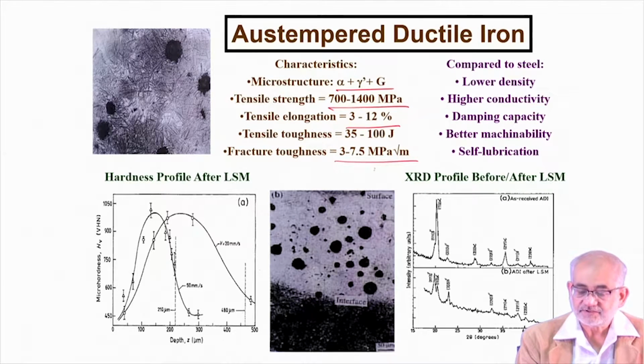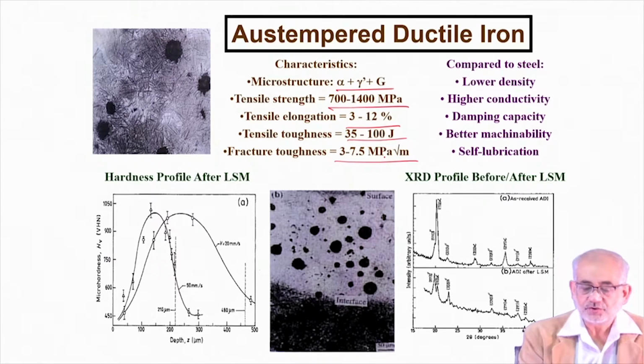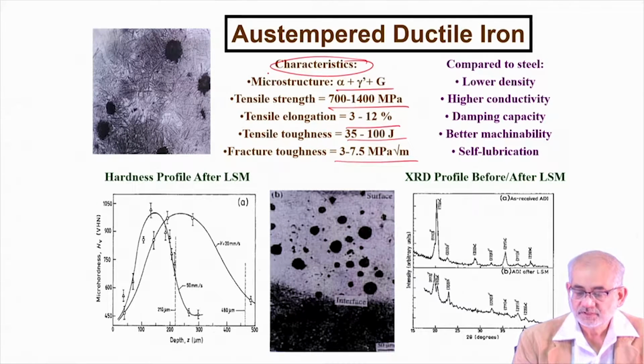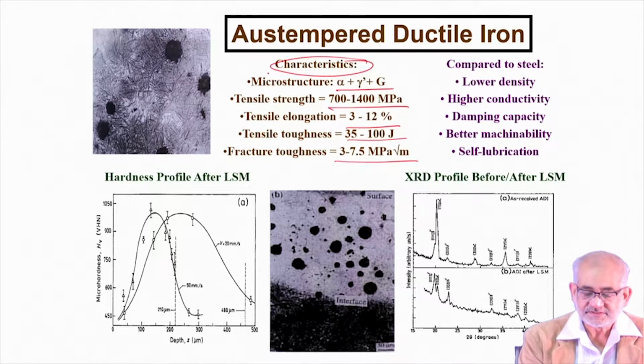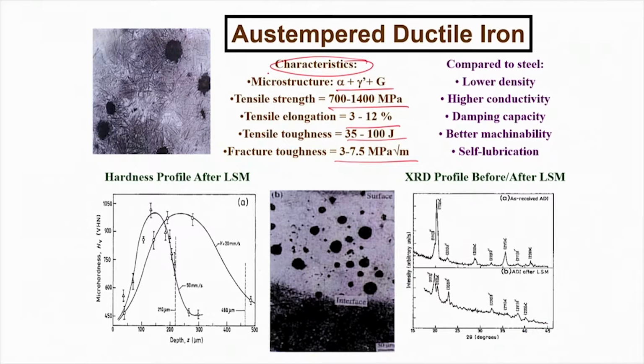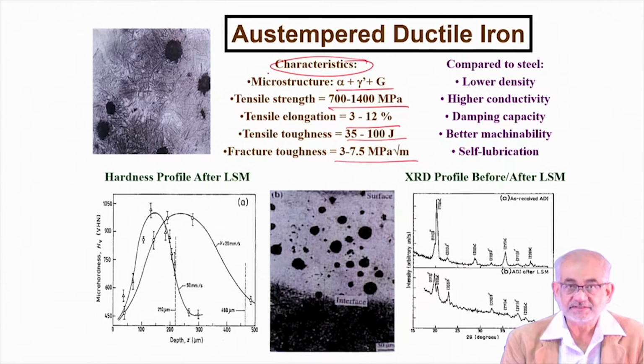Also, in addition to that, we have both high tensile toughness and also higher fracture toughness. So, all these characteristics of Austempered ductile iron, or spheroidal graphitic iron with bainitic microstructure, make it a very, very important material for various products, including engine blocks and various cast products. Like in this particular case, we are talking about the application scope of ADI for excavator shovels. Now, let's not worry about exactly which component we are talking about.